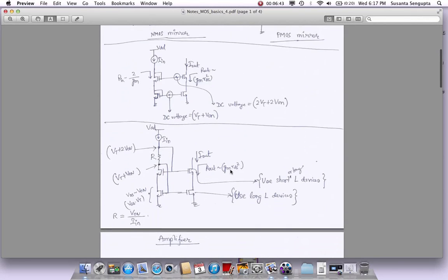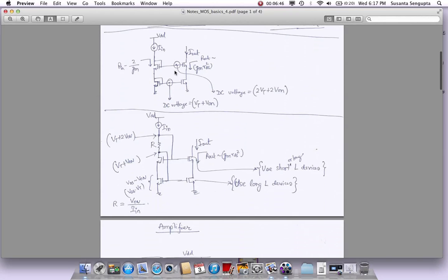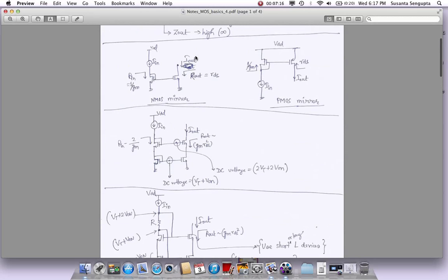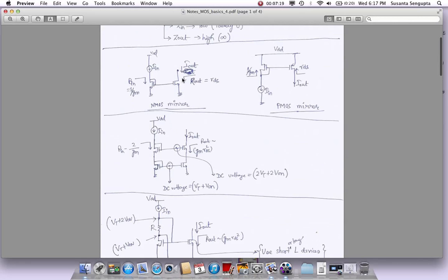So we looked at the simple current mirrors. Now let's look at how we can improve the output impedance. We did go over a cascode earlier, and we showed that when you have a single device and you put a series MOS device with it, the output impedance really gets boosted. Roughly, it is the Gm of this device times the RDS of this device multiplied by the RDS of this device. If we say all the RDSs are roughly equal, it becomes Gm times RDS square. Previously, looking down, you had only RDS. Now you have boosted it by a factor of Gm times RDS.